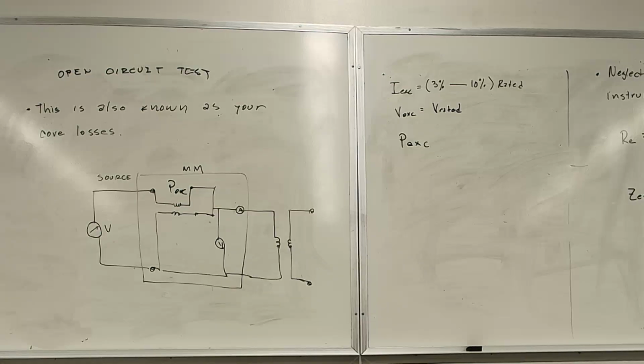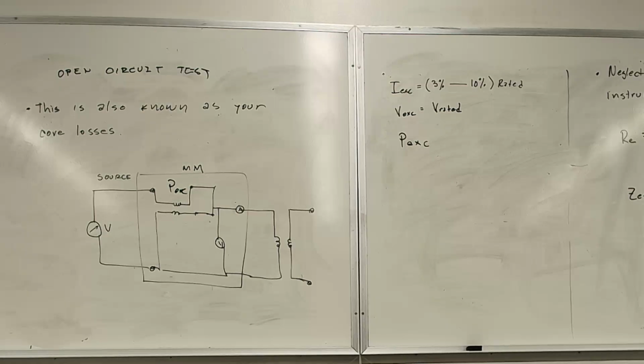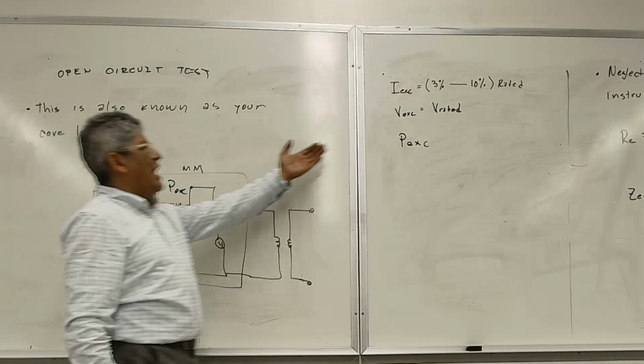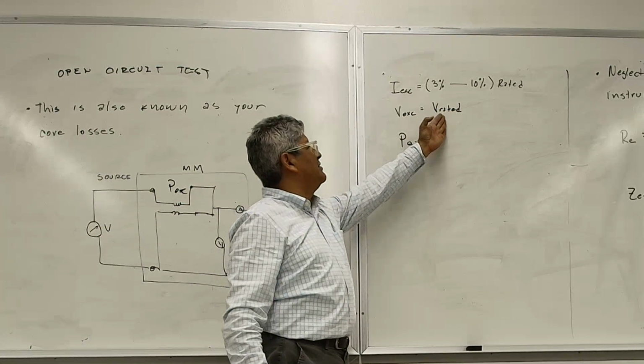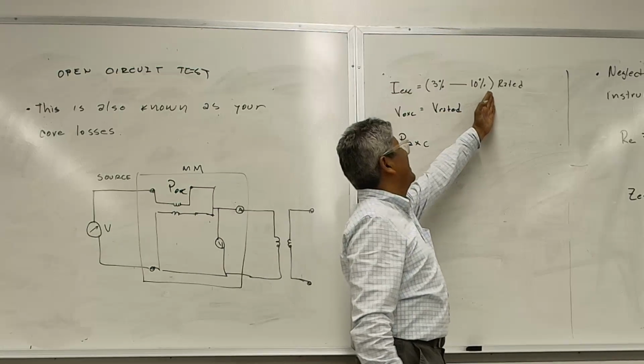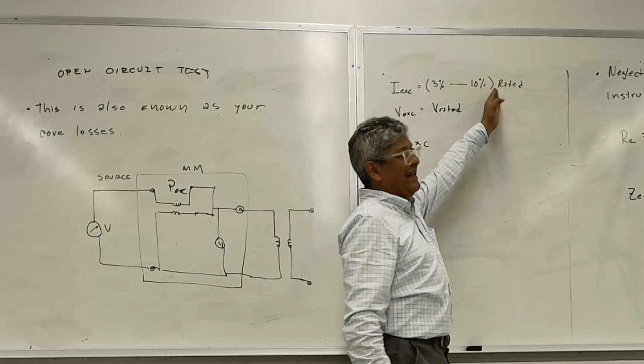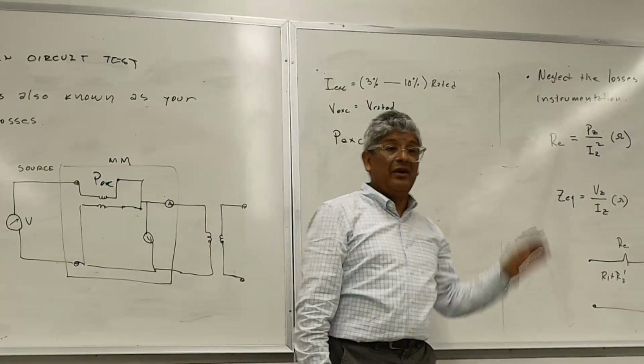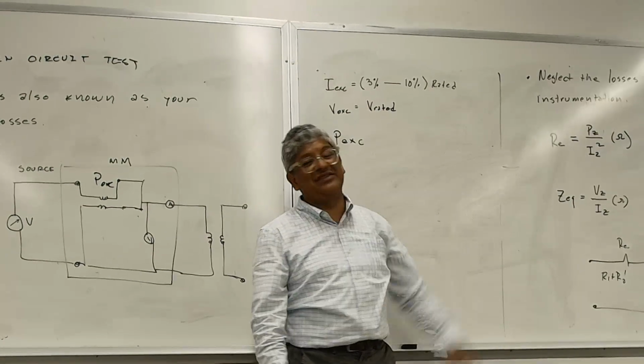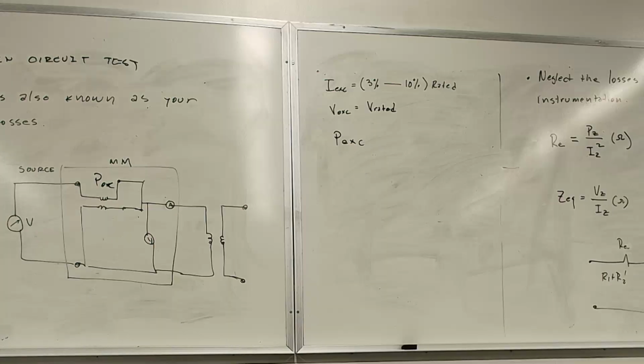So the machine is locked. We put a heavy load on the shaft. Sometimes the load is not high enough to get it to that value that we get rated, and the machine will start moving, right? But we can still assume that is standstill. Similarly on the transformer, the point I'm trying to make is I'm gonna raise the voltage all the way to this rated value. Say for instance, instead of 3 to 10%, I get 11%, that's fine, it's good enough. What I don't want here is to get too rated, otherwise I can damage the transformer itself. Do I make sense, everybody?